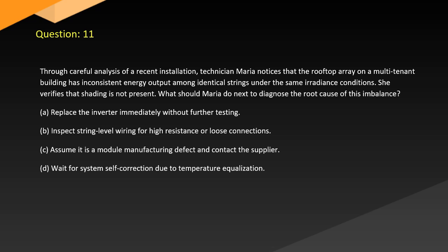A. Replace the inverter immediately without further testing. B. Inspect string-level wiring for high resistance or loose connections. C. Assume it is a module manufacturing defect and contact the supplier. D. Wait for system self-correction due to temperature equalization.